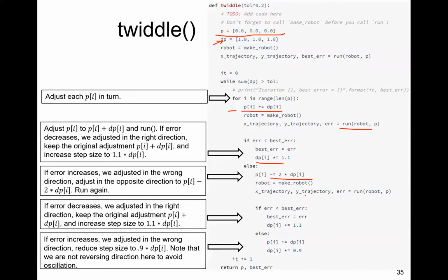But this is good, it might work okay. But from a strict control point of view, you should adjust them all at the same time in some way. Yeah, so twiddle is strictly a heuristic. So obviously you can add additional rules to the heuristic. For example, the rule of decreasing the P parameter when you increase the I parameter. So all of these can be added. So this is just a very simple heuristic. Yeah, sure. Good enough, I think.